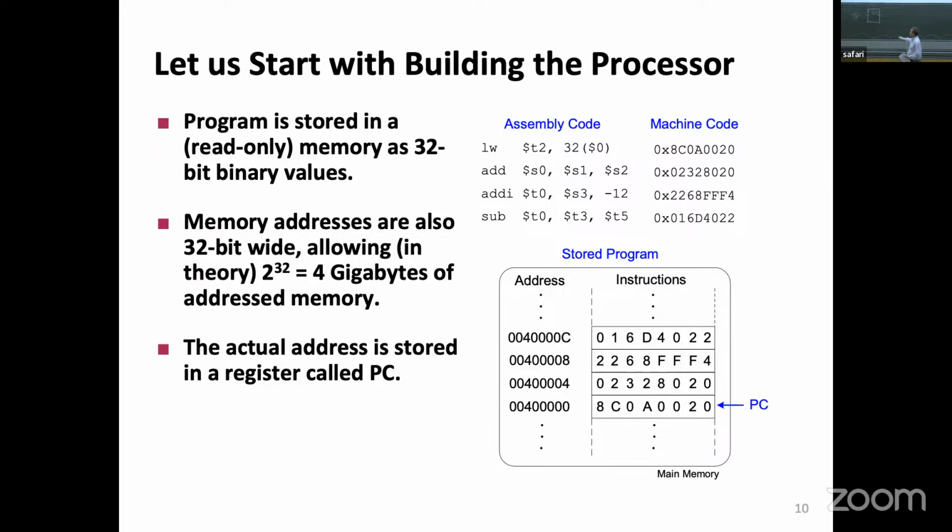So somewhere I have to realize that, hey, I am actually doing an R-type instruction. How do I know that I'm doing an R-type instruction? Well, I will check the bits 31 to 26. If all 6 of them are 0, I know that I'm doing an R-type instruction. Who's going to do the checking? We will come to that in a little while. It will happen down here.